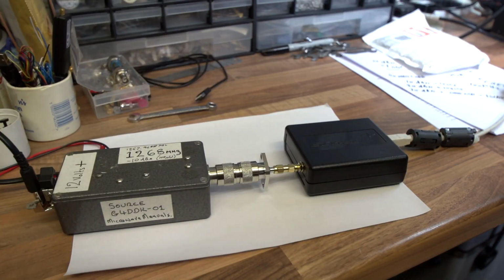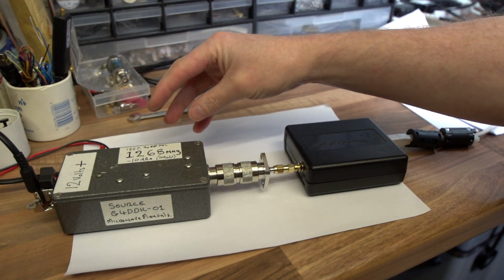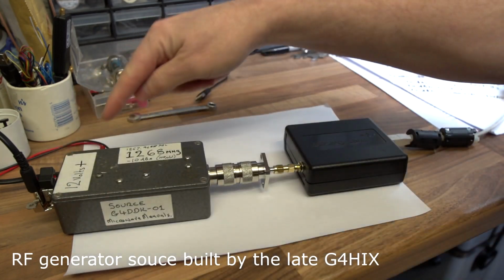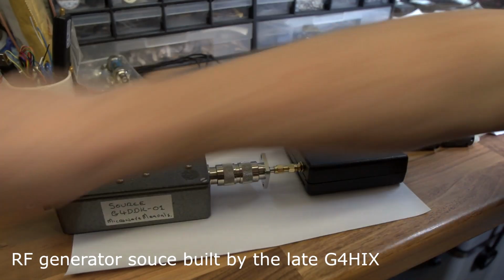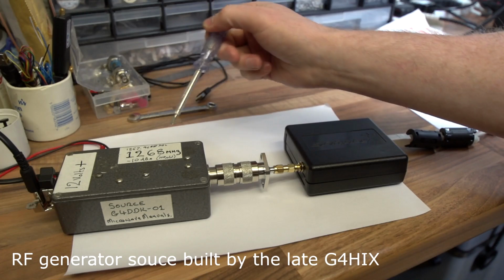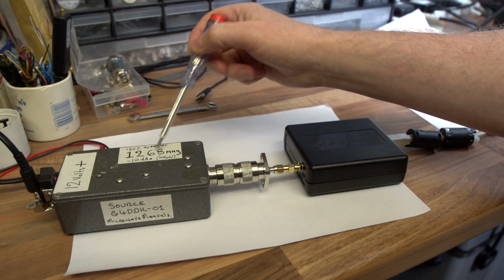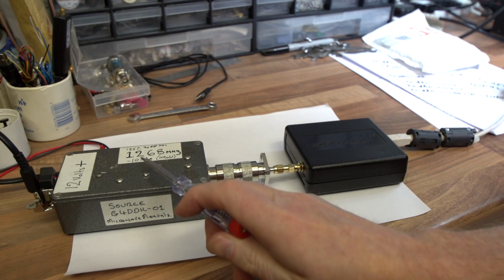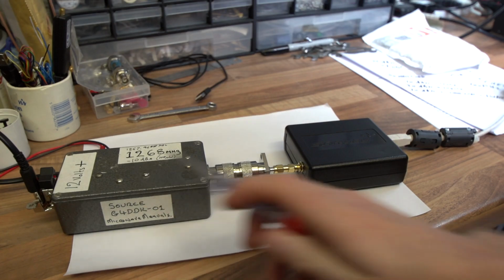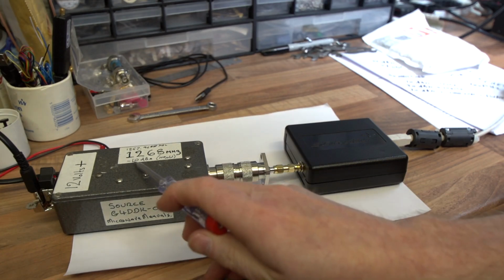Okay, so here's an actual practical example of using a spectrum analyzer. What we have here is a homemade frequency source or signal generator device. It runs on 12 volts, and it's being supplied from the power supply. All this is really a high frequency oscillator. It's written on the case what the frequency is, 1268 megahertz, which is 1.268 gigahertz. It's also written on here, because it's already been calibrated, minus 10 dBm. So that's the output level we expect from the output here into a 50 ohm load.